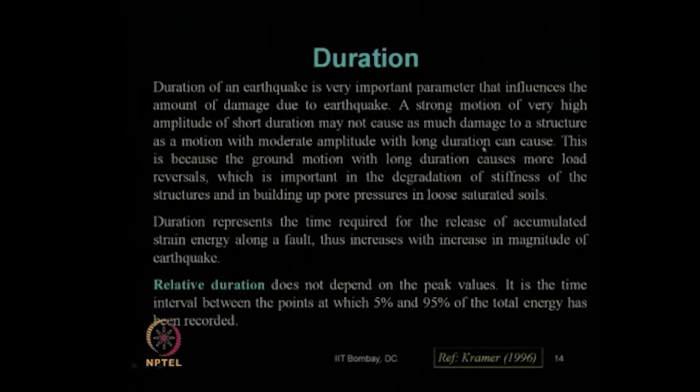That I have already mentioned in my previous lecture, that it is not necessary that a very large magnitude or amplitude earthquake will always cause major damage. If it occurs for a very short duration, it may not cause large damage, because the structure did not get enough time to respond to that large magnitude.